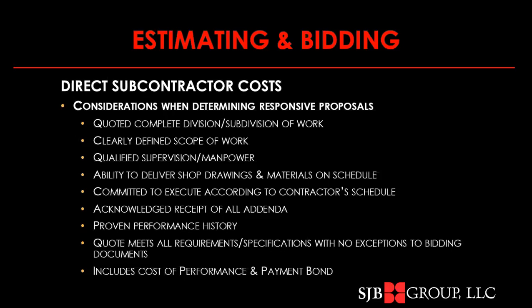Does the quote clearly define what is included in the scope of work in the quotation? Can the subcontractor provide qualified supervision and sufficient labor to meet your project's requirement? Does the sub have the ability to deliver shop drawings and materials to the job on schedule? Has the subcontractor committed to your schedule? Has the subcontractor acknowledged all addenda in making the quotation to you?